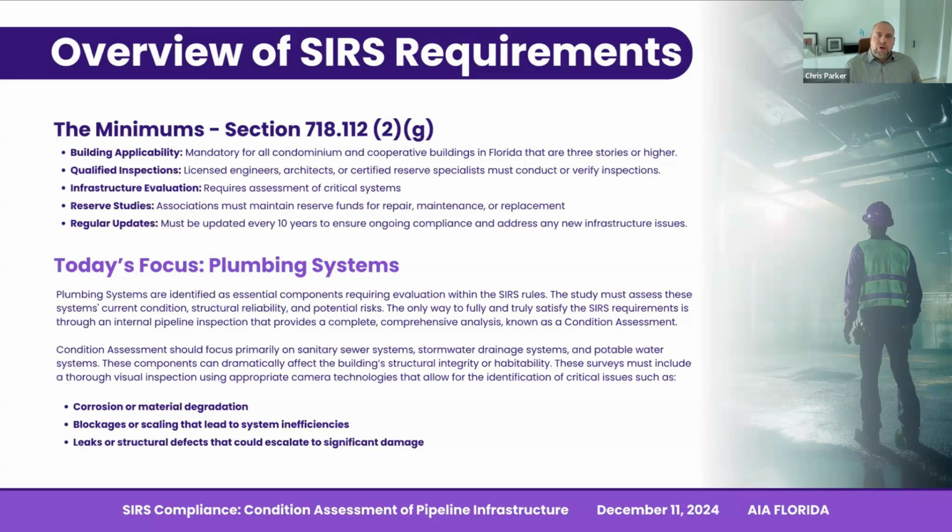So that's generally the life expectancy of a cast iron pipe system. If you get into certain other materials in newer buildings like PVC, they do have a much longer life. They have different failure points within those systems. But again, generally speaking, most sewer systems in a high rise are going to be rated between 30 to 40 years. Nowadays, if it's a newer building, that can get to be 50 years plus. So great question though.